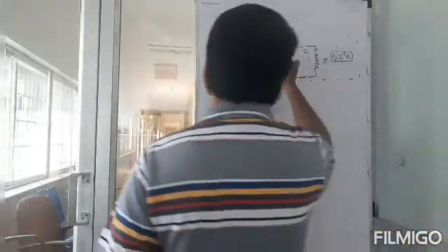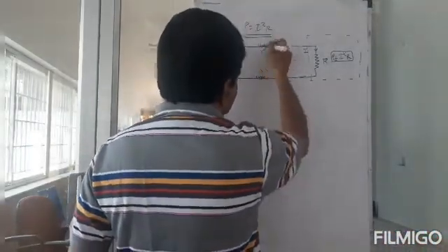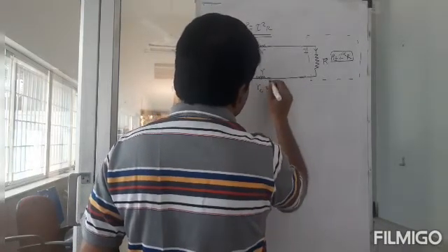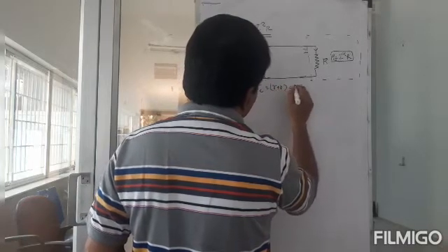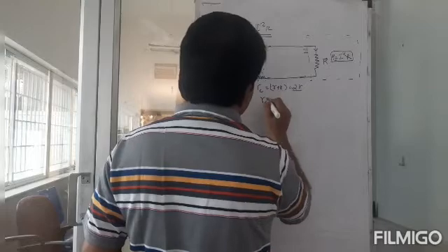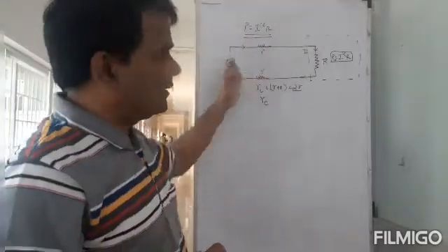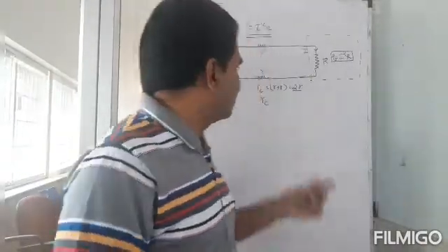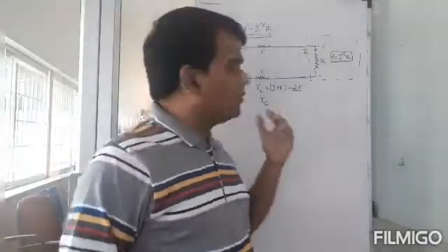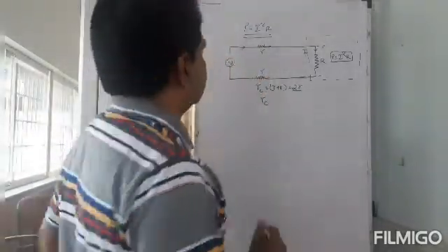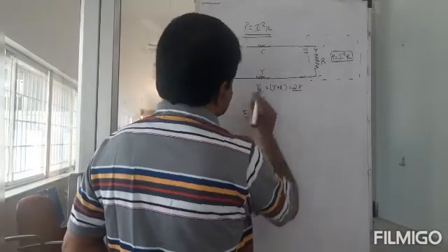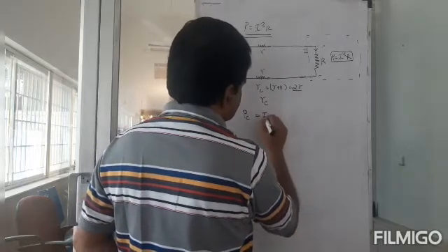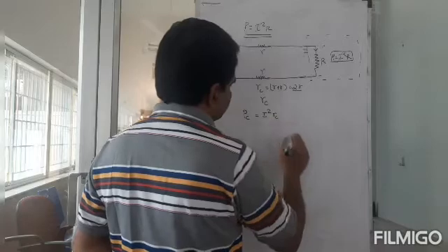I'll say that is, let me take this R and R together, and I will call it 2R, which is equal to RC. RC is equal to R plus R. Okay? 2R. I'll just take RC. RC represents the resistance of the lines. Okay, so this is RC. Okay, the power loss in the conductors is going to be this, right? So PC in the transmission is equal to, say, I squared into RC.